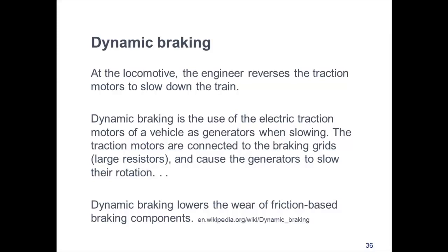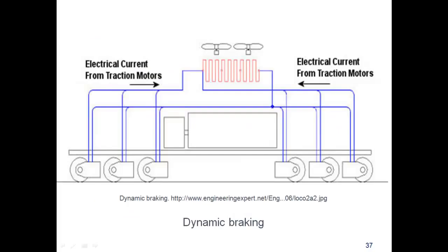And Dick, would this analogy be right? Dynamic brakes are like downshifting into second gear when you're driving down a hill to slow the car instead of braking to save on the brake pads? That is an appropriate analogy. With a diesel locomotive train, the generated electric power is dissipated as heat in brake grid resistors. The electric energy goes into the atmosphere. For an electrified train, the generated electric power can go back into the grid via the catenary. The word regenerative is used when power travels back into the supply grid.